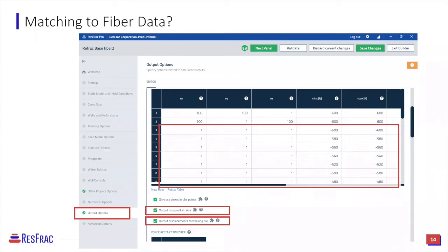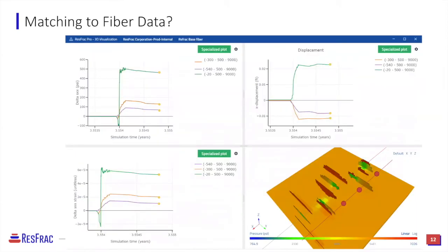Hey, I'll just make a comment. So you're showing how you're outputting not only stresses, but also strains or displacements. And it's worth briefly thinking about what is the measurement that's actually recorded at a fiber. So a fiber is really measuring displacement at a series of points. And so when they provide a strain rate, what they're doing is they're taking the difference in displacement between 2 points, and that's how they report the strain. But those points are not directly adjacent to each other.